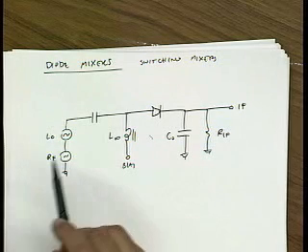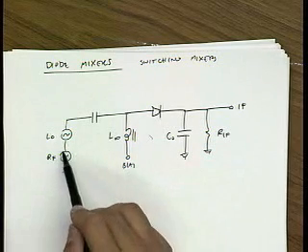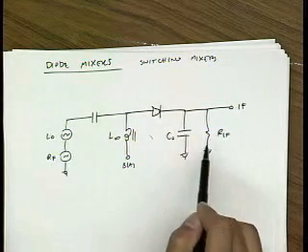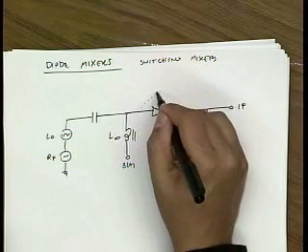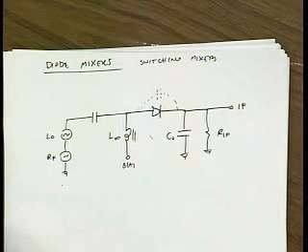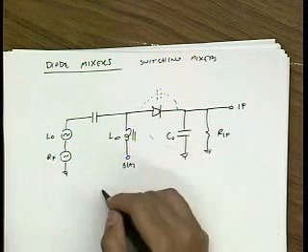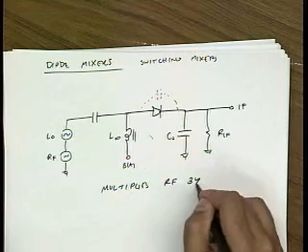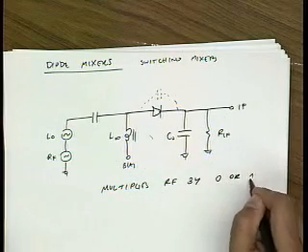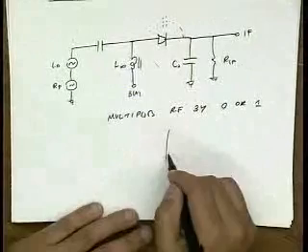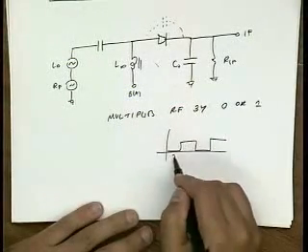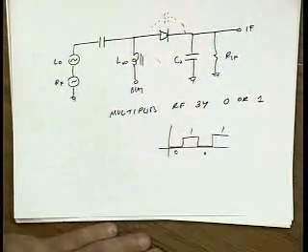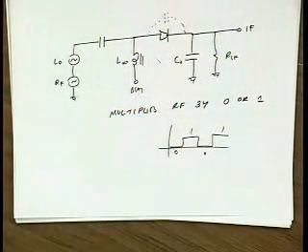Half-wave rectifier. So during a positive LO cycle, the RF is connected to the output. During a negative LO cycle, the RF is isolated from the output by basically the feed-through capacitance. So this circuit multiplies RF by 0 or 1. Okay? And so it looks like a time-varying transfer function, and we get mixing action from it.